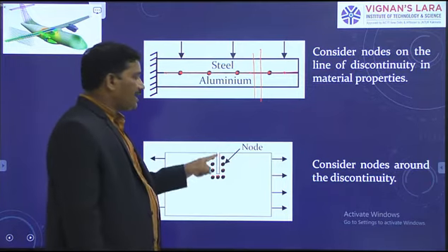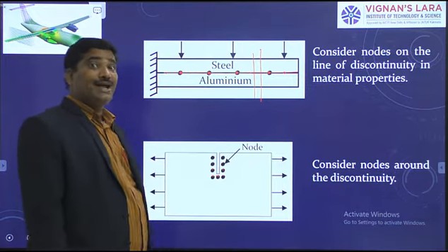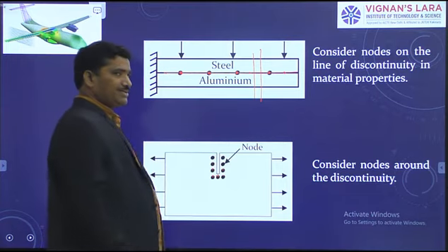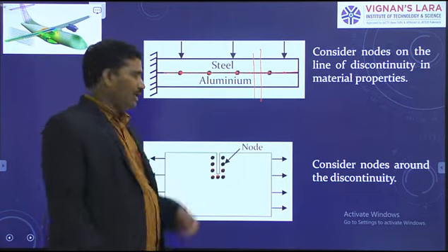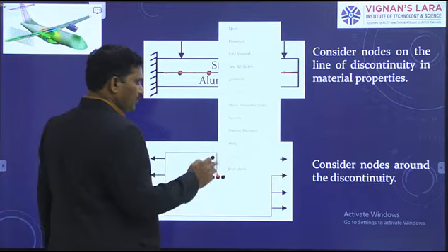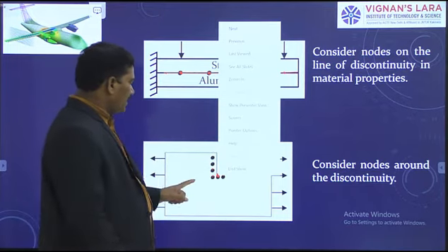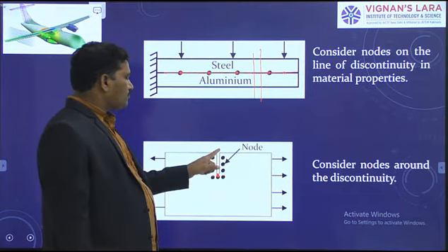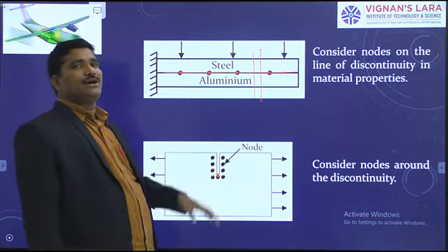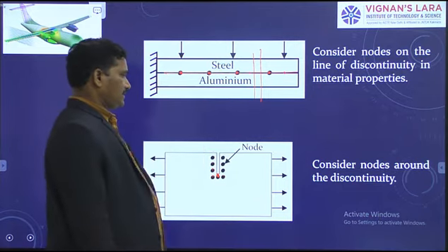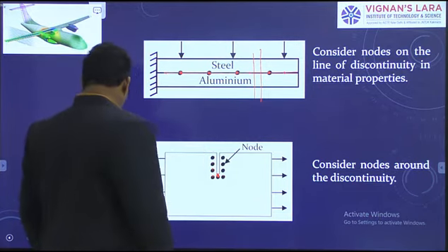Stress concentration is more in the vicinity of the discontinuity. Therefore, we have to take the nodes as many as possible around the discontinuity when you solve a problem using the finite element method. Right?